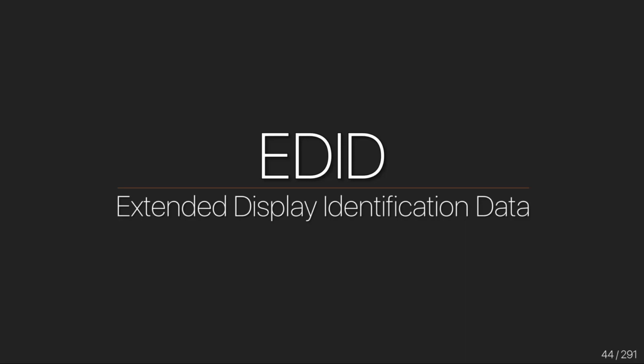So a hop would be if you've got an HDMI cable and it's coming out of an output port and then into an input port on a device, that would be one hop. And then if that device then has another output port and another input, let's say, that would be another hop. So effectively, I would consider it as the amount of HDMI or DVI sort of links you have in the system. Yeah. All right, I think that's it.